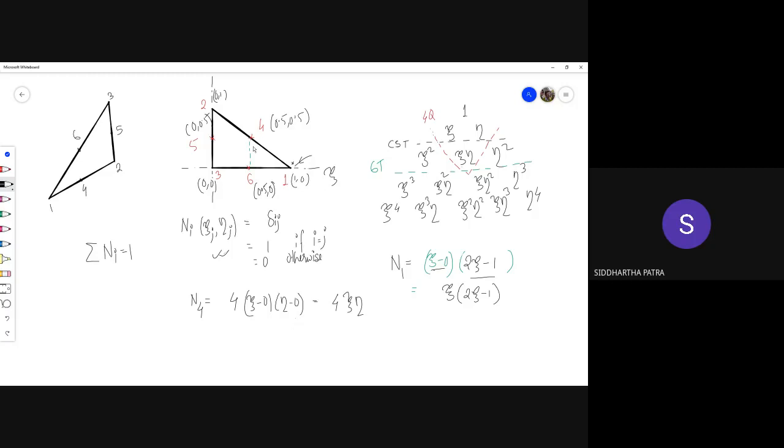Okay, and we would try to construct each of these shape functions by taking the minimum number of such straight lines. If we ensure that, then this would automatically be satisfied everywhere within the geometry. That is what's supposed to happen: whatever the expressions of the Ni's are, if you sum them up, the net value is going to be 1.